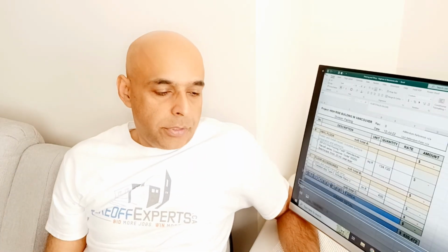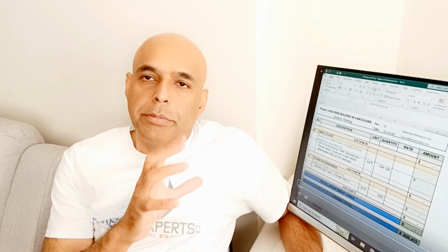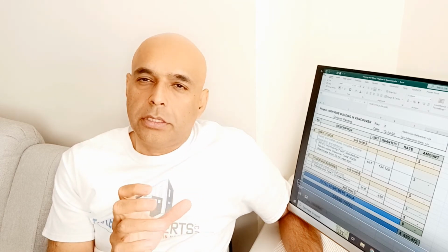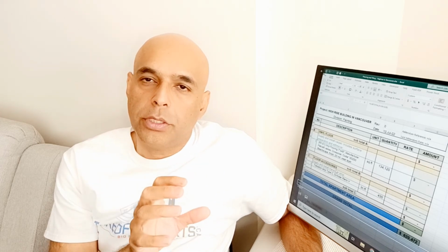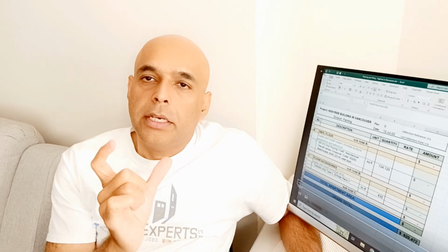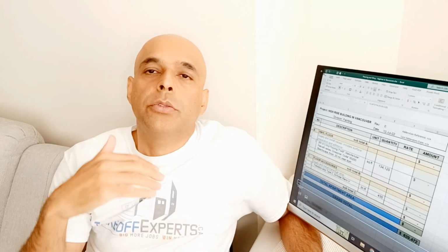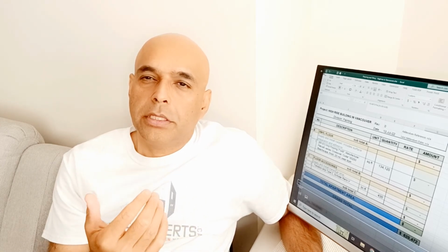So that's it. I hope you got a bit of an idea of the process that we use to do all the measurements of all the individual areas, and how we make legends in the Bluebeam Takeoffs software, and how we transfer all the individual measurements into the spreadsheet, and how we total everything and then transfer all those subtotals into the main spreadsheet, which is the BOQ spreadsheet, which is what the flooring contractor will be using to get pricing from his supplier and build his quote.